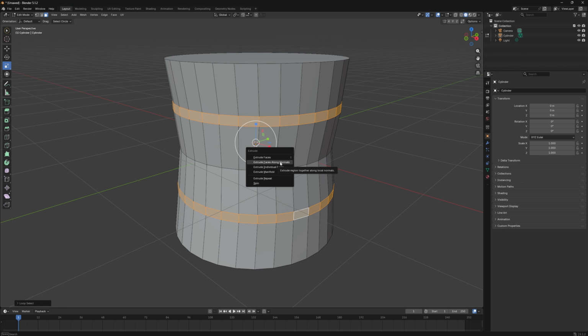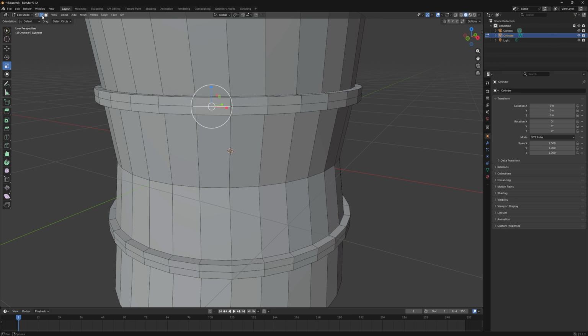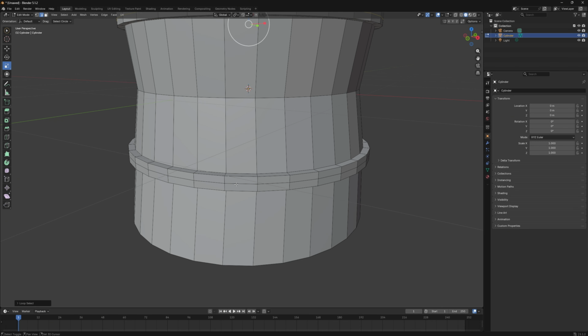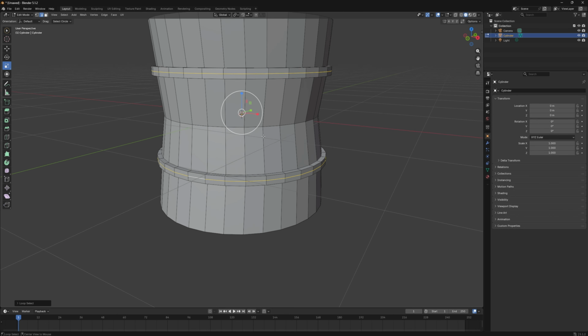We're going to press Ctrl R and make sure we're on this vertical part of the mesh here, and we're going to just simply click and leave it in the middle. We're going to do the same for the one down here. So we're going to click and just double click so it stays in the middle. And what we're going to do is make sure we're in edge select mode, and we're going to hold Alt and Shift, and that will select all around it. Move down, Shift and left click, Alt and Shift, and that will go all around that area as well.